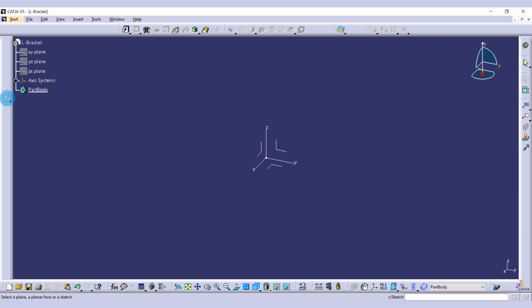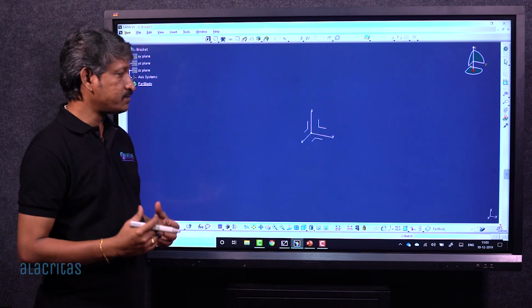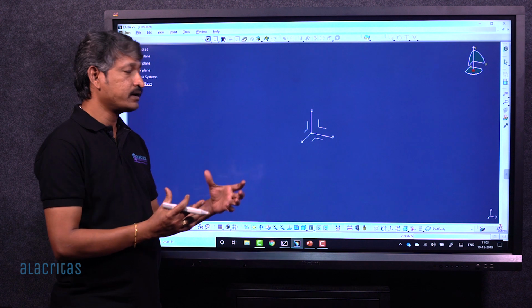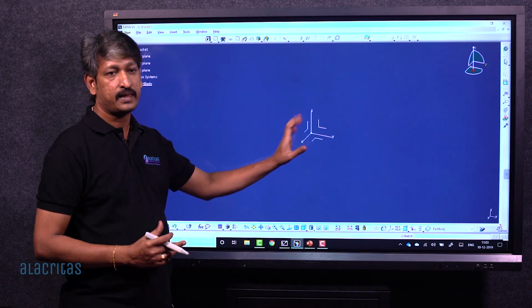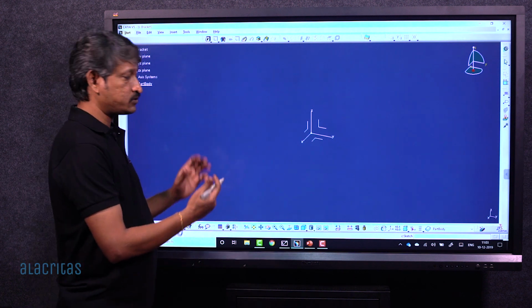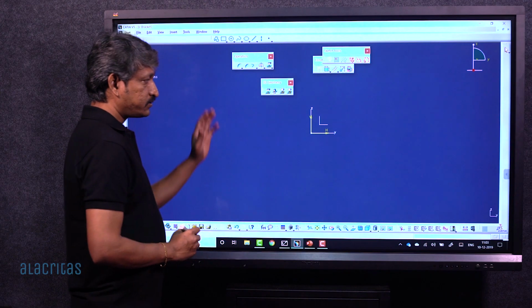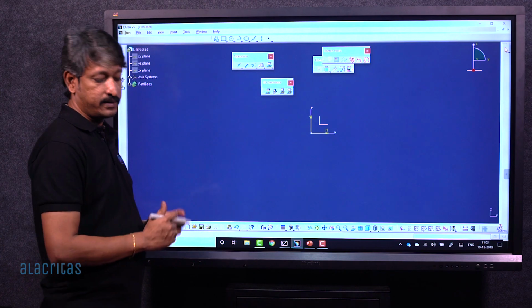Let's go to the Sketcher workbench and select the Sketcher icon. Before choosing the plane, just keep in mind how it will look in the isometric. Based on that, we have to select our primary plane, and the sketch has to be appropriate. So in this case, we'll take ZY as our sketch support. Select this and let's draw a simple L and make a pad.